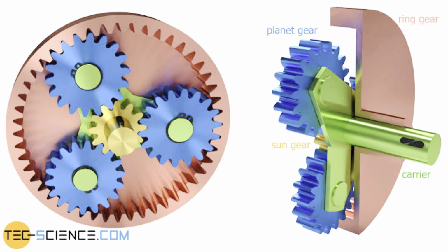Planetary gear sets. Automatic transmissions contain many gears in various combinations. In a manual transmission, gears slide along shafts as you move the shift lever from one position to another, engaging various sized gears as required in order to provide the correct gear ratio. In an automatic transmission, however, the gears are never physically moved and are always engaged to the same gears. This is accomplished through the use of planetary gear sets.